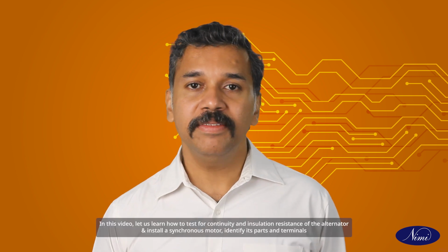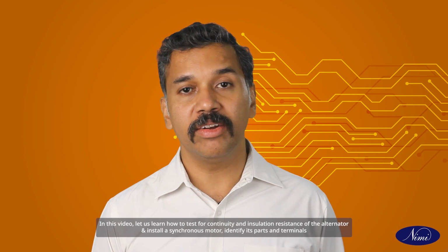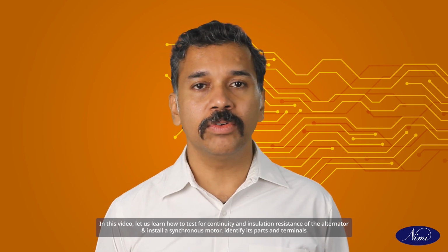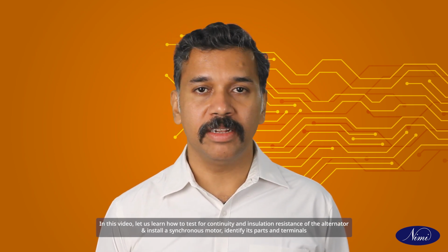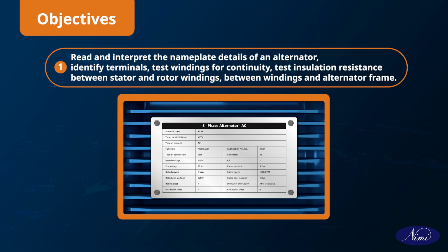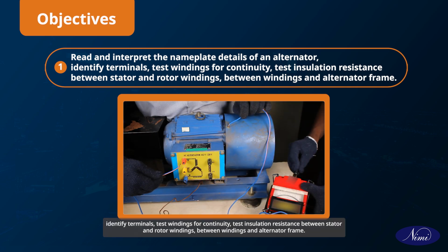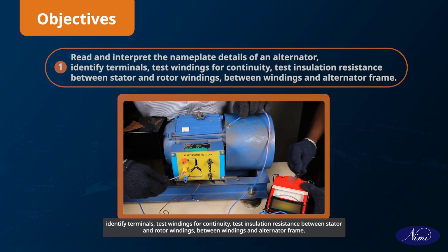Hello everyone. In this video, let us learn how to test for continuity and insulation resistance of the alternator and install a synchronous motor, identify its part and terminals. At the end of this video, you will be able to read and interpret the nameplate details of an alternator, identify terminals, test windings for continuity, test insulation resistance between stator and rotor windings, between windings and alternator frame.